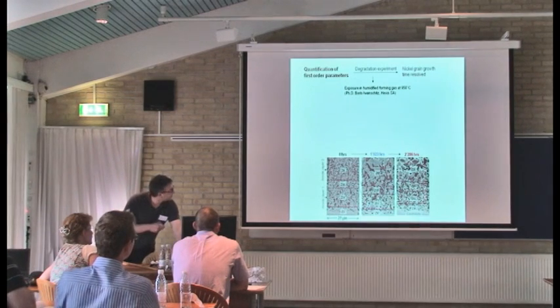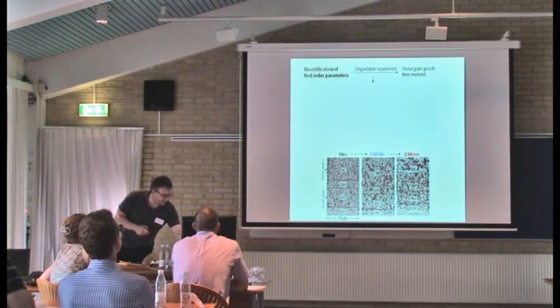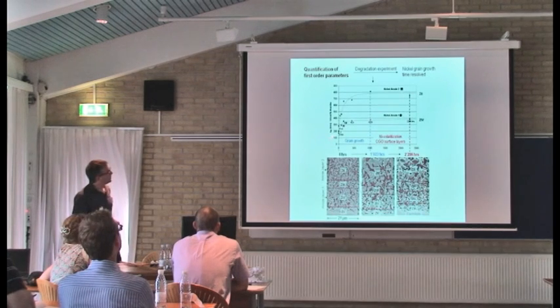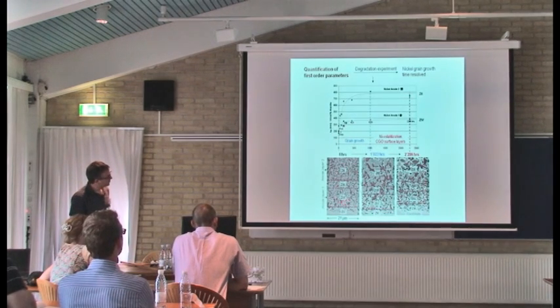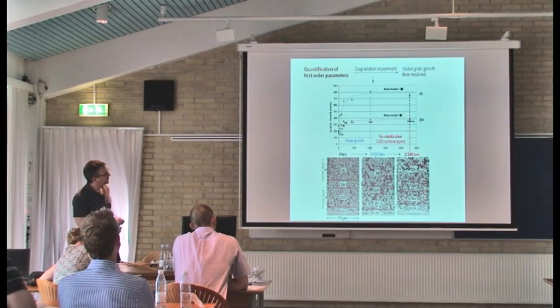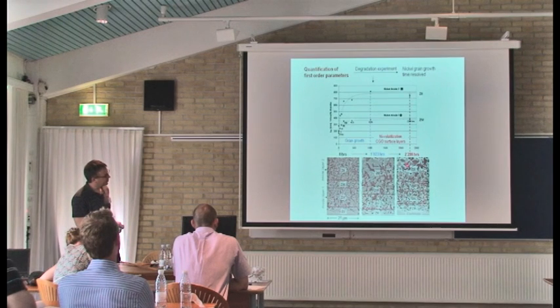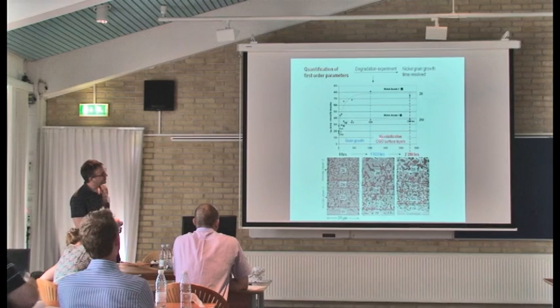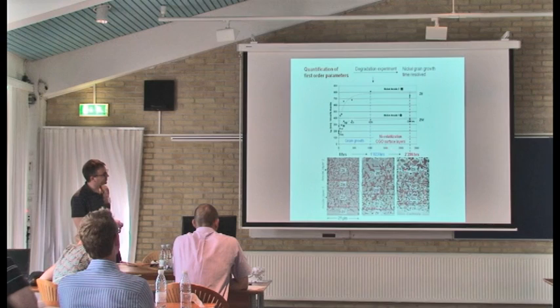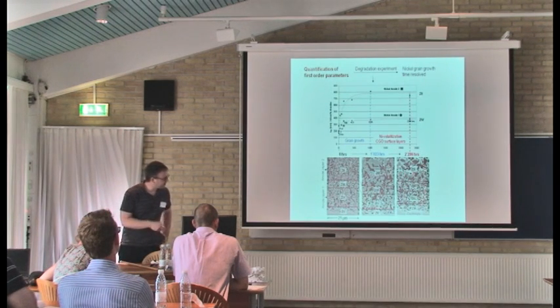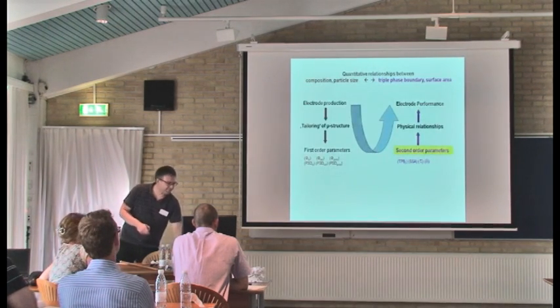These are experiments that were done in a humidified forming gas. So you see in this zone 2 and zone 4 how over time the average size is changing. You have fast grain growth in the beginning, and then nickel is not growing anymore, but we have different other processes. There is evidence for volatilization of nickel and also formation of surface layers of CGO. But the nickel grain size remains the same.